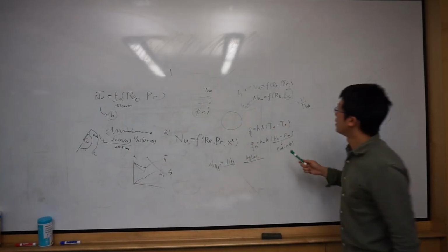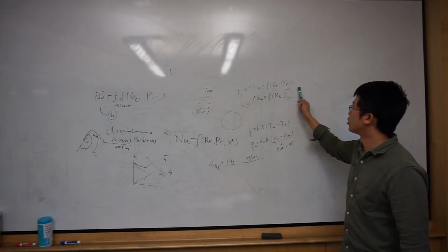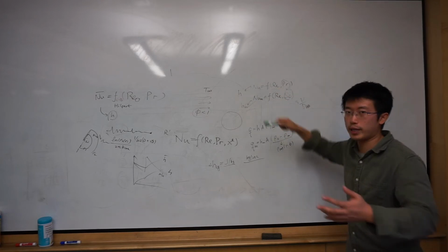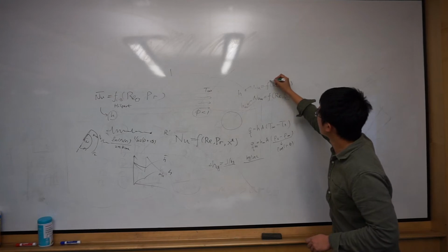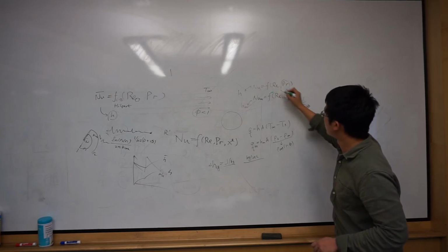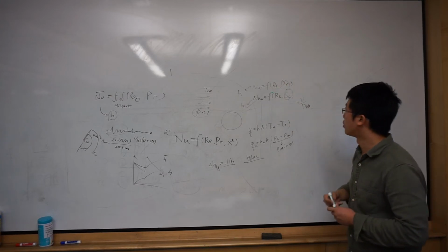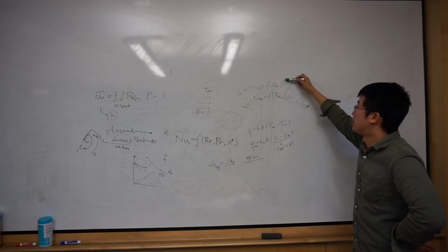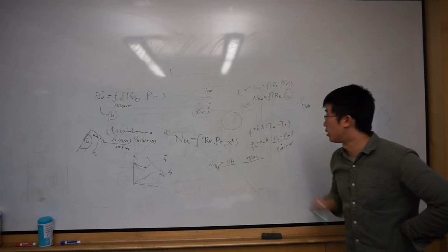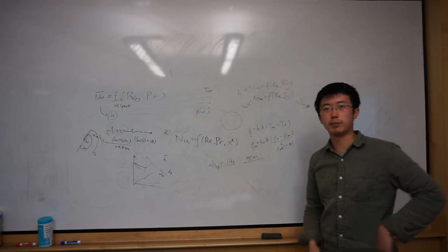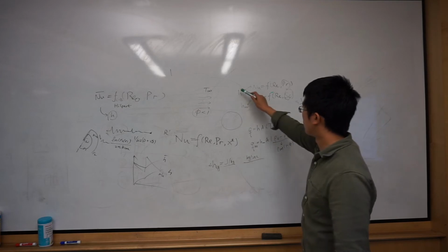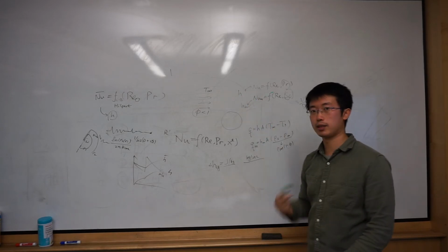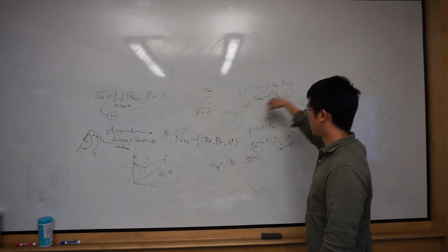We just mentioned that these two cases look like two different correlations, but they share the same Reynolds number. So the only difference is to replace the Prandtl number in the correlation with the Schmidt number, and you will get the mass transfer Nusselt number. Then calculate these two numbers separately. Each of them can be a separate problem, but now we combine them together.